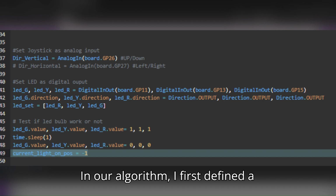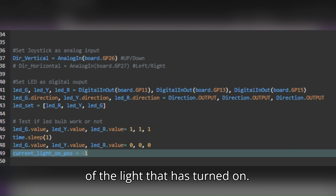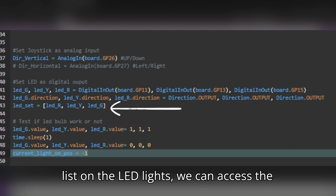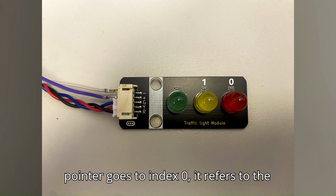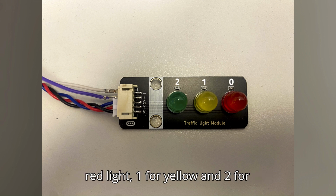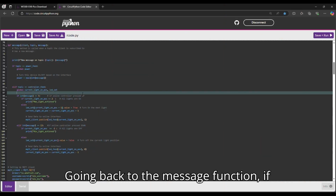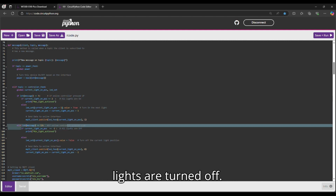In our algorithm, I first defined a variable that tracks the current position of the light that is turned on. By making use of the previously defined list on the LED lights, we can access the sequence of light. That means that as the pointer goes to index 0, it refers to the red light, 1 for yellow, and 2 for green. Going back to the message function, if the pointer is equal to 2, it means that all lights are turned on, and if the pointer is equal to -1, it means all lights are turned off.